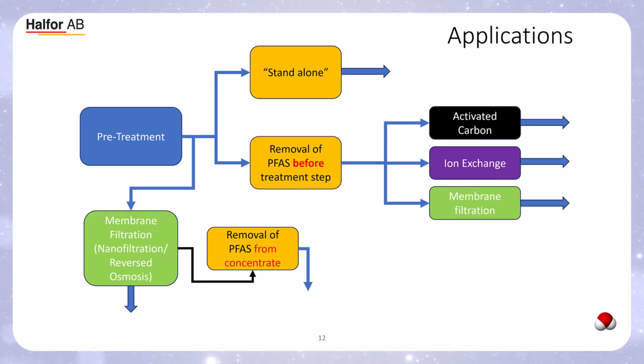Then if you have PFAS in your raw water that you treated with membrane filtration, then probably foam fractionation will be quite interesting to use to clean up the reject from the membrane filtration. And I mentioned in the water tank chat 12 that the reject from the membrane filtration project can range between 10 to 50% of the feed flow, so to speak.